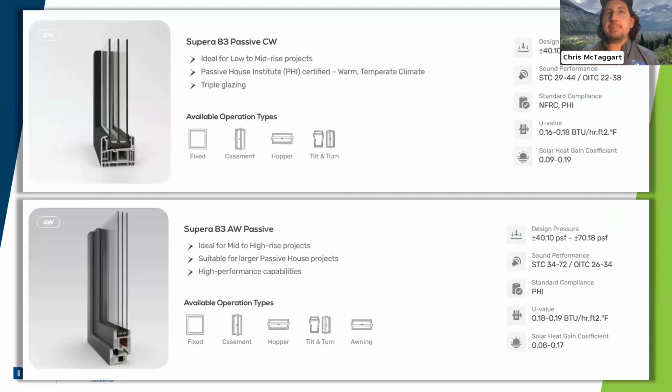You know, this is a side profile of some of these really good high performance windows that have very low overall U factor. And again, the solar heat gain coefficient can vary. I mean, some of these, honestly, solar heat gain coefficient is kind of low. Again, you got to be careful. Maybe now we're not going to have very much visible transmittance coming in through them. But you get an idea here of at least how high performance windows like this may be constructed.